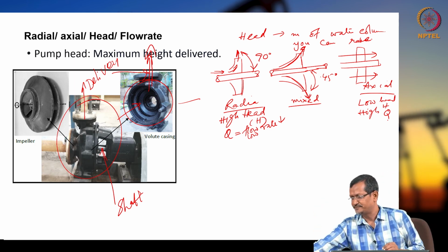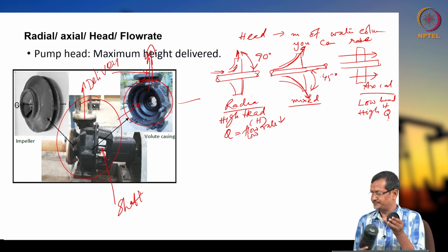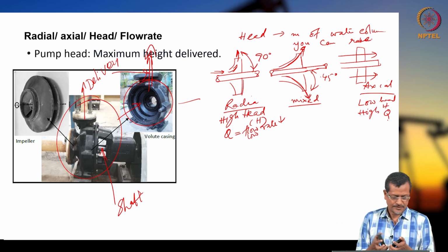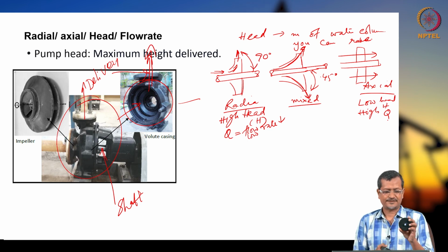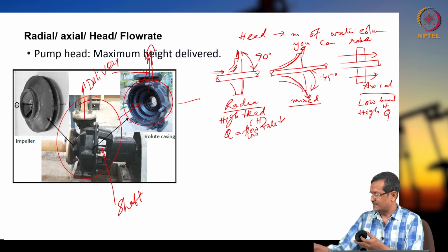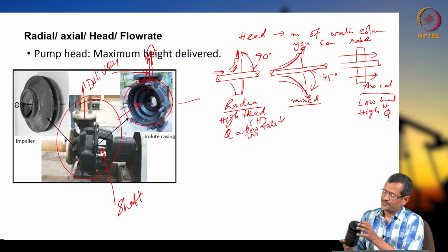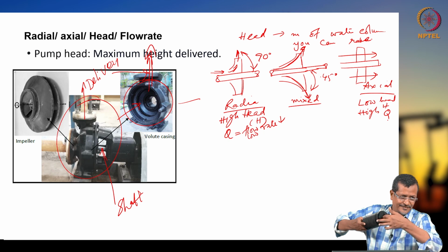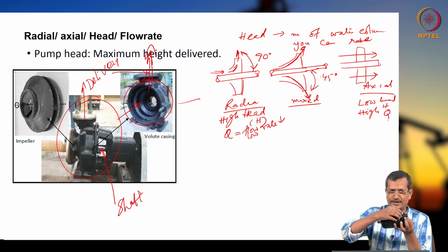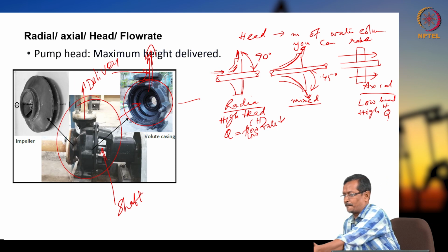I have another model. This is an actual ESP system, electric submersible pump system. So, multiple staging, how multiple staging of a centrifugal pump is done. So this is radial flow. I have a small impeller. This is also radial flow. It has an eye. This is the shaft, this one is the shaft. And if you see, the eye is here, above. Inside, the impeller is exiting here. I don't know whether it will be coming through on camera. Impeller exiting here. Okay. Then my casing is here.